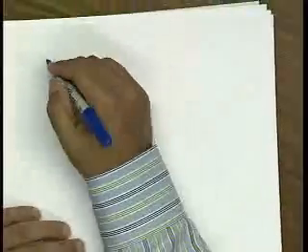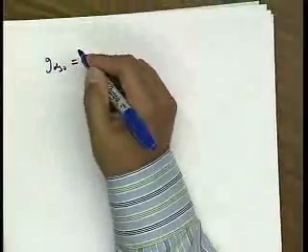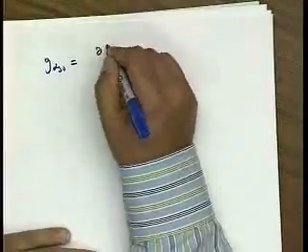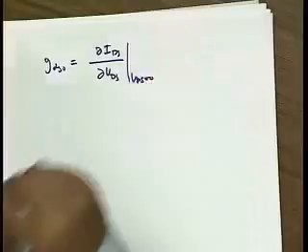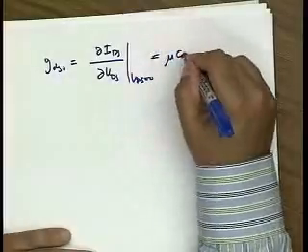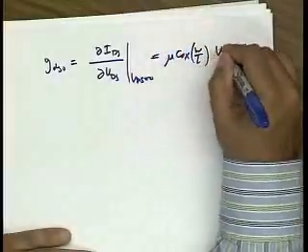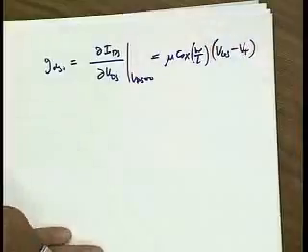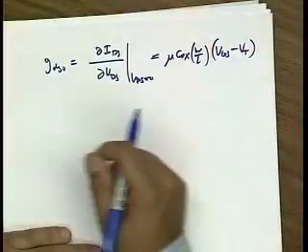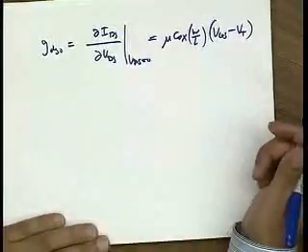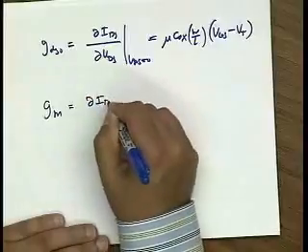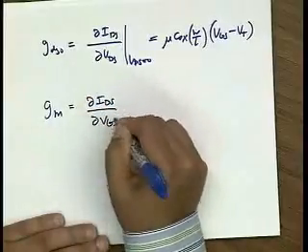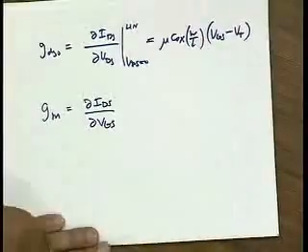So GDS0 is equal to the derivative of IDS versus VDS when VDS is equal to 0, and that's simply mu C ox W over L (VGS minus VT) for a long channel device. Well, it's actually kind of interesting that if you look at the GM of a transistor, so this is basically the linear region equation because VDS is equal to 0.